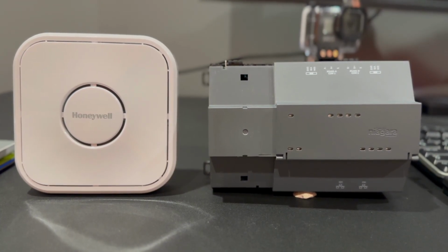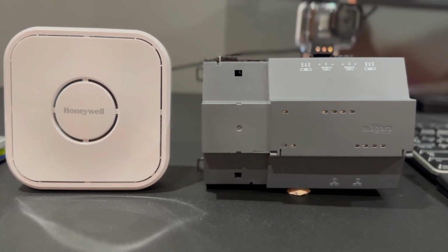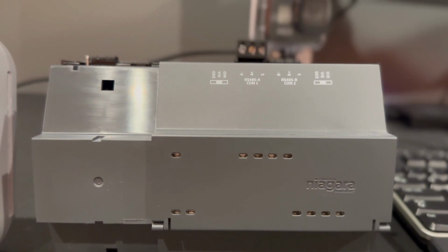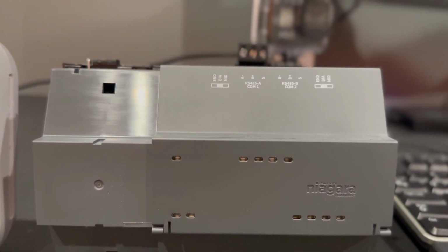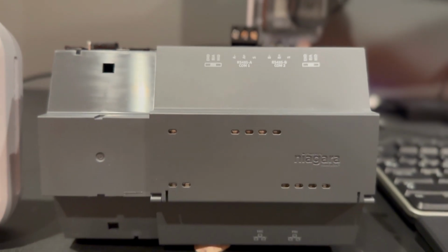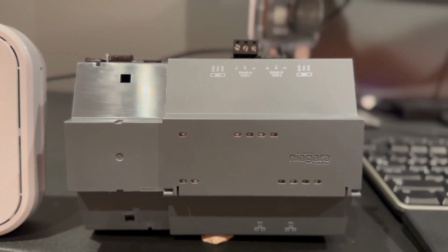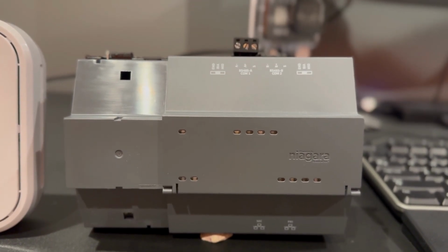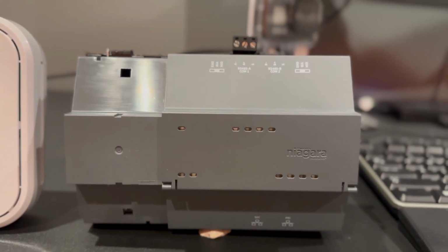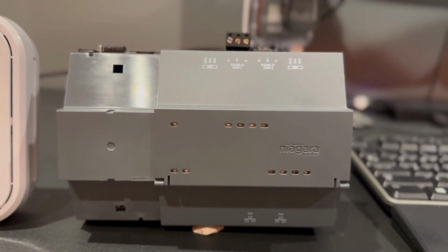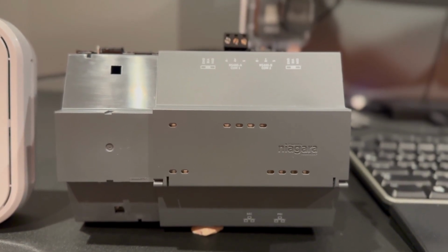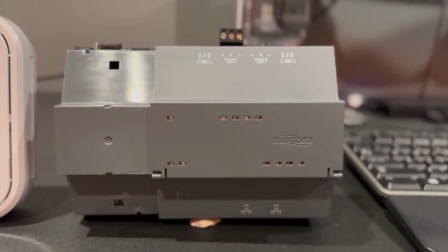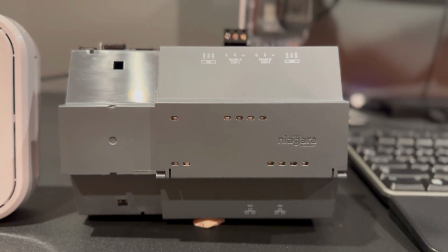We'll be connecting the sensor to the JACE, which you see here, and as you can see, the JACE has an RS485A terminal with A plus, A minus, and a shield. So your TX and RX is going to be wired into these two terminals. Positive and negative does matter when it comes to Modbus. I will show you further where TX or RX goes to in the JACE, and let's see how we configure Modbus once you get into the JACE.